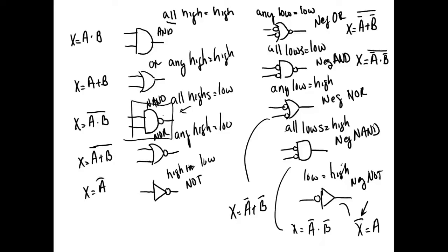TTL is pretty forgiving about leaving gates in there set up, but CMOS, we'll show you that too. Them suckers will switch on anything. So what y'all need to do is either tie the unused inputs up or tie them down. Any questions on this? Ask them now. Now we're moving into that whole sheet. Everybody's got that sheet.